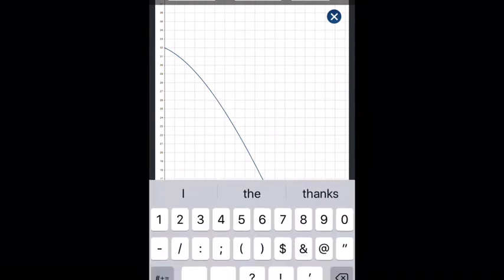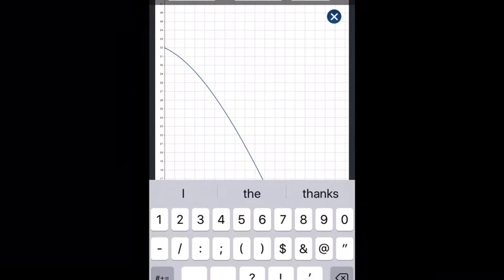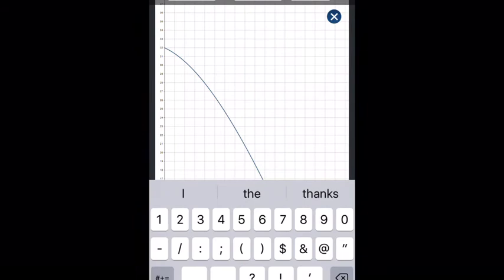So let's go ahead. I'm going to tap that pump curve. So I just touched it, and this is what pops up. So the Q is going to be the flow rate. Now what I would do is use what you determine as the flow rate. So if you figured out based on the BTU output divided by 500 times your delta T calculation, and you determine the flow rate, use that one.